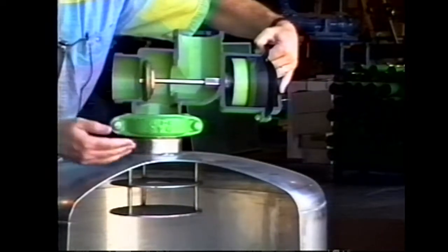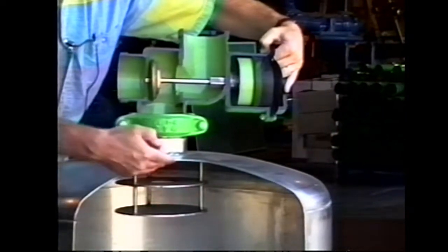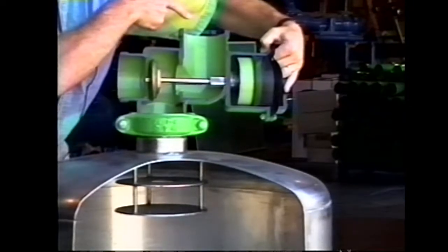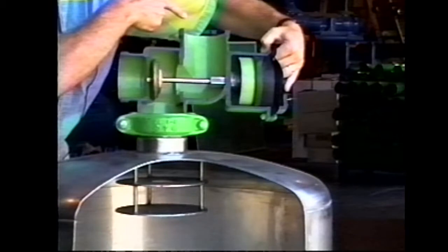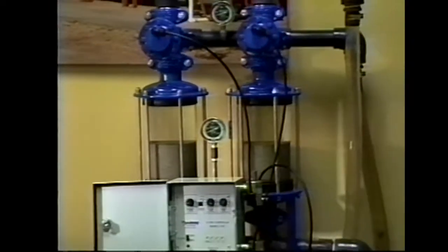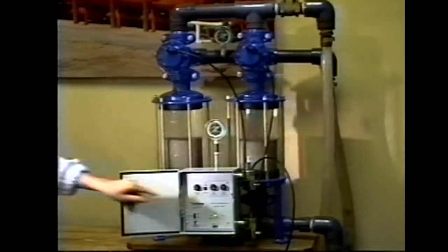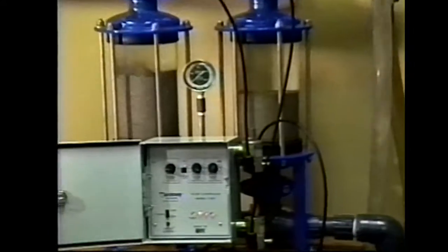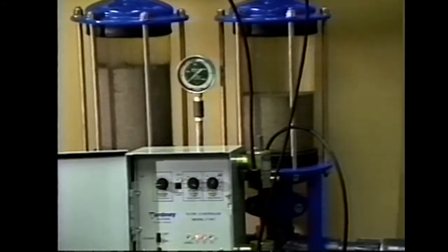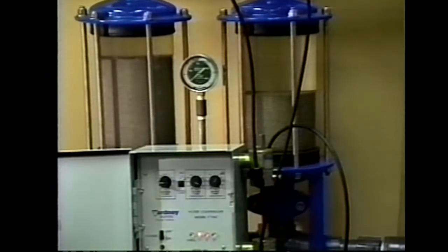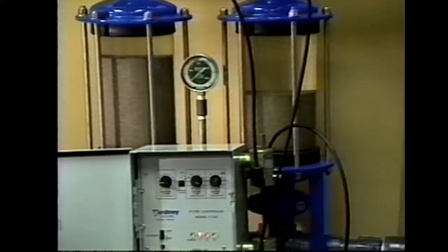During backflushing, three-way valves on the top of each tank change position, one at a time, shutting off the incoming water, opening an outlet to the atmosphere, and allowing water from inside the tank to exit. Underdrains at the bottom of the tank allow clean water to flow back upwards through the tank. The clean water for backflushing must come from another tank, as shown here with this model. One tank is backflushed at a time. When the media is fluidized during backflush, the dirt which was trapped on the top of the media bed is flushed up and out of the tank.